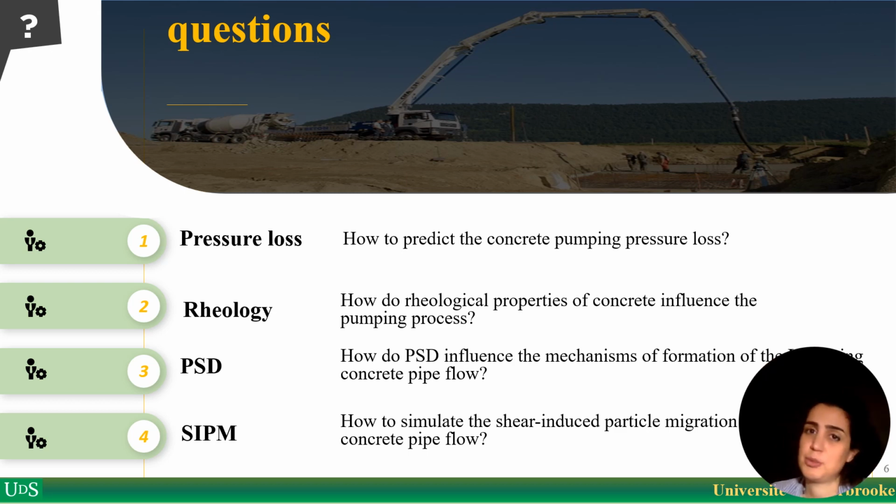Actually, we use numerical simulation to answer some important questions. What is the pressure loss of the concrete pipe flow, or how can we reach a more accurate prediction of the effect of the rheological properties of the concrete and lubrication layer on the behavior of the concrete pipe flow? What is the effect of particle size distribution and particle concentration on the formation of the lubrication layer? And in the final step, we use numerical simulation to model shear-induced particle migration, which is an important phenomenon in the formation of the lubrication layer.